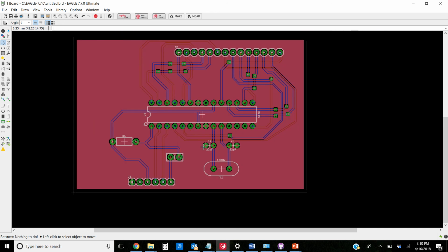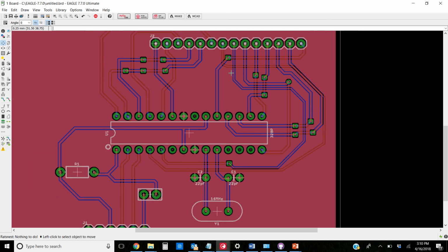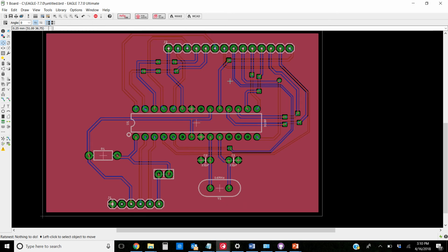So really about the most basic Arduino you could set up. But this doesn't really show us what all of these pins are. When we go to manufacture this, we wouldn't know what any of these pins are. We'd have to reference our schematic and diagrams, and that would be a pain, right? When you go look at an Arduino, there's white writing or silkscreen on this, and we'd like to do the same so that we know what everything is when we go to it.